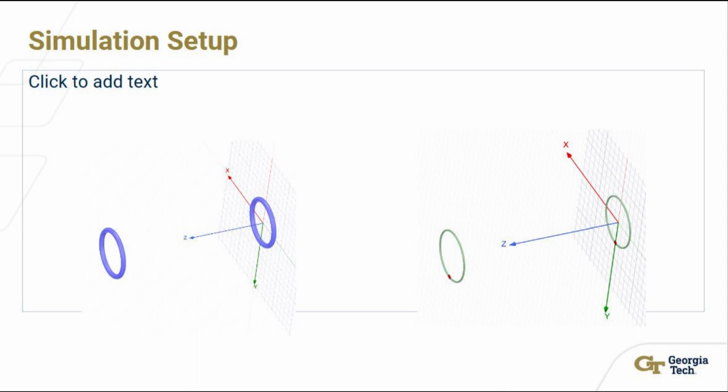In the picture on the left, we can see the PVC wrapping that is to prevent any surface interactions with the saltwater that decrease the transmission strength. In the picture on the right, we can see the internals of the antenna. In green is the copper conducting part of the antenna. In red is the lumped port of the antenna. This is where the antenna is excited. Not pictured is the radiation boundary set around both antennas. This is filled with salt water and mimics the ocean that we want to simulate. After this model has been set up, we run an analysis.